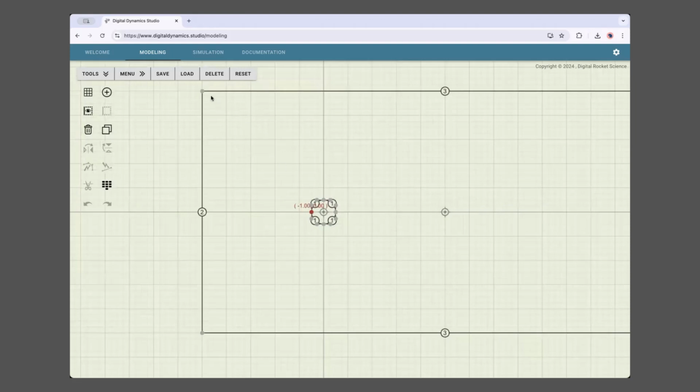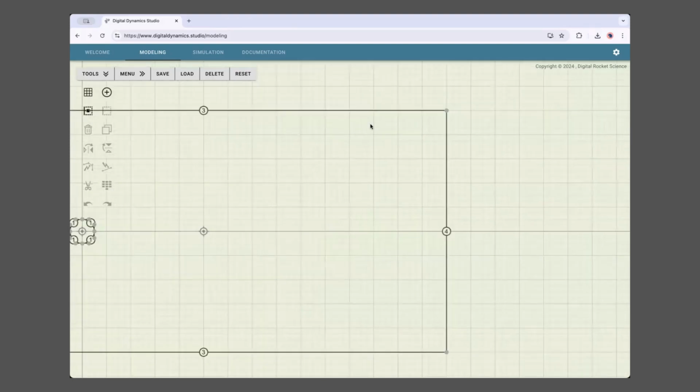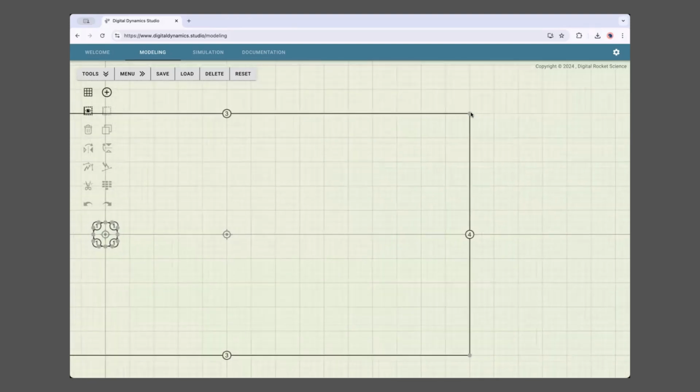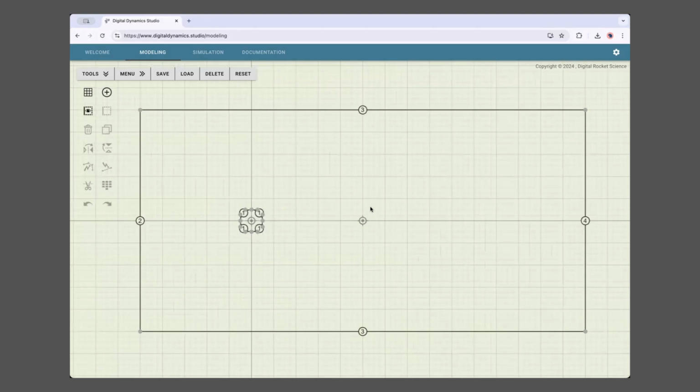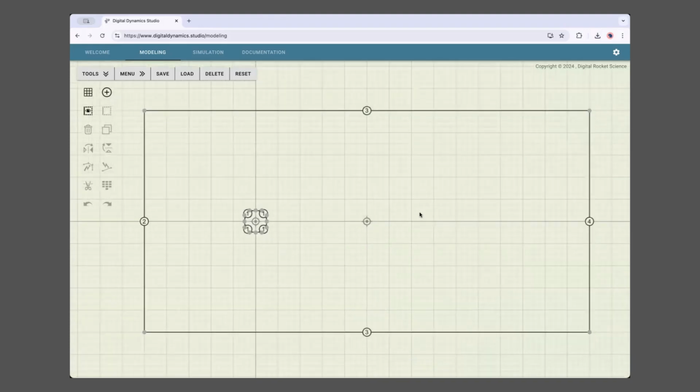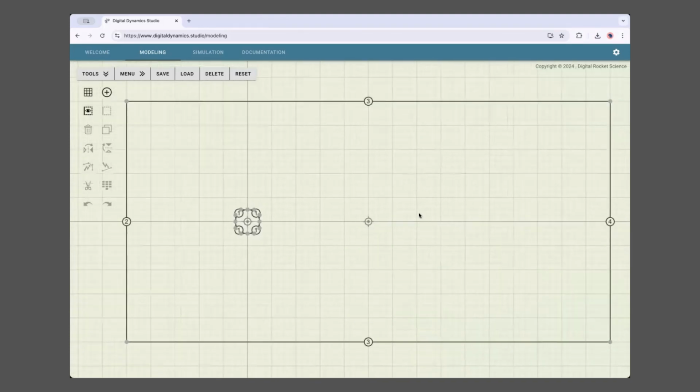We wanted the inflow boundary corner to be at +10, -10, and yep, that's exactly the way we wanted it. We wanted the outflow boundary to be 30 units downstream, and yep, 30. So basically this model is exactly the way we want it to be, exactly as we described in part 1 of the tutorial. So this is actually set up properly, and this is what we want in the simulation.